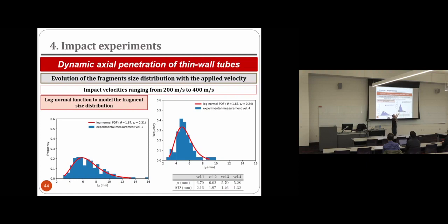This is very typical. In this particular material, if we follow the ideas of Mott, the theory of Mott of fragmentation in the 40s, as we increase the loading velocity, the unloading waves emanating from early cracks don't have time to travel the specimen, and more cracks are formed and developed. Therefore, we have more cracks, more fragments of smaller size. This is a trend that we obtained for all the experiments that we were performing.